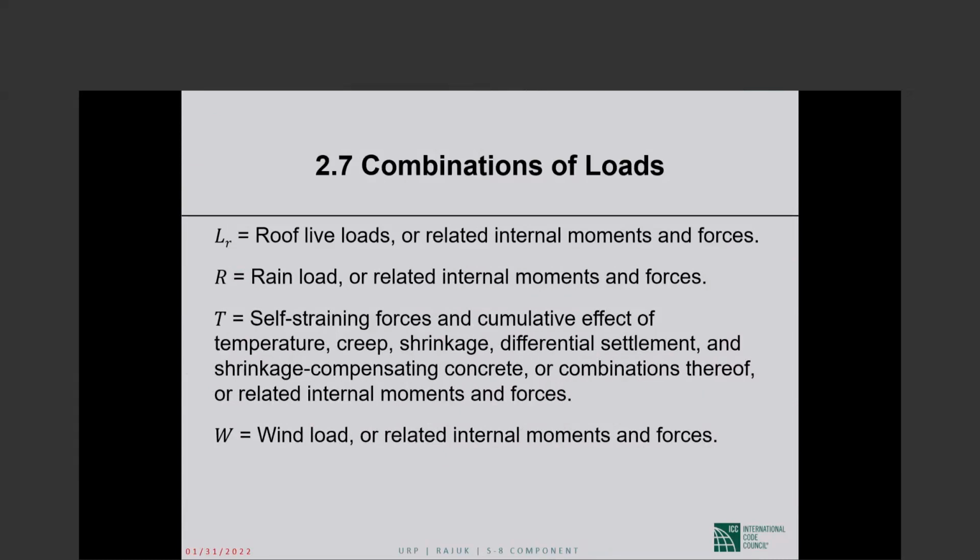Restrained volume changes. Okay, volume change may be because of temperature rise or fall, or volume change may be because of shrinkage. As water evaporates out of the concrete, it shrinks. If the concrete is allowed to shrink, there is no problem. There is a little bit of shortening, but that typically is not an issue.